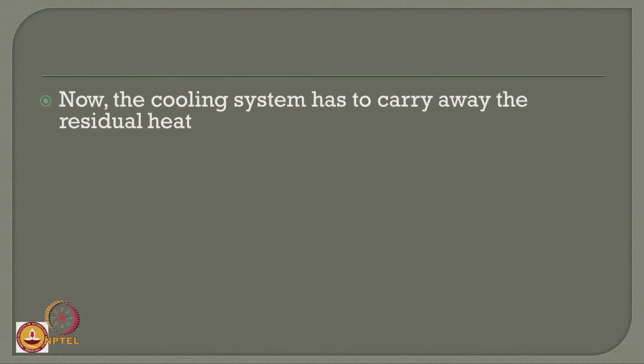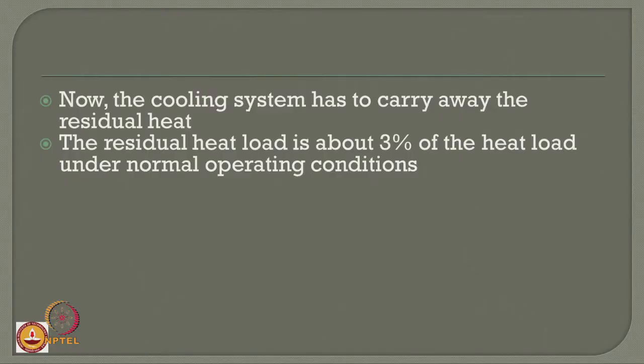Now, the cooling system has to carry away the residual heat, because the reaction has stopped, but the heat is present. This heat has got to be removed and cooled down. So, the cooling system present in the design itself has to carry away the residual heat generated inside the core. This residual heat is about 3% of the heat load under normal operating condition, which is the generally anticipated value.